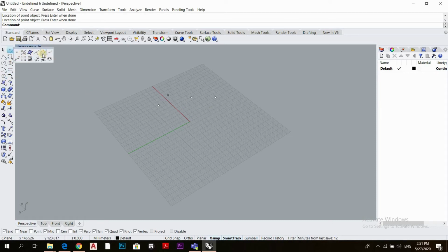There are other commands here, like extract point. If I have a surface, I can extract points from it. When we get to surfaces and we draw a surface, we'll see how we can do that. How can we get the points out of it? That would be something useful for someone that's working on a topographic map, and he needs the points from it. He has a 3D model, but he needs the points, so he can extract them from here. That would be the most used things in points.